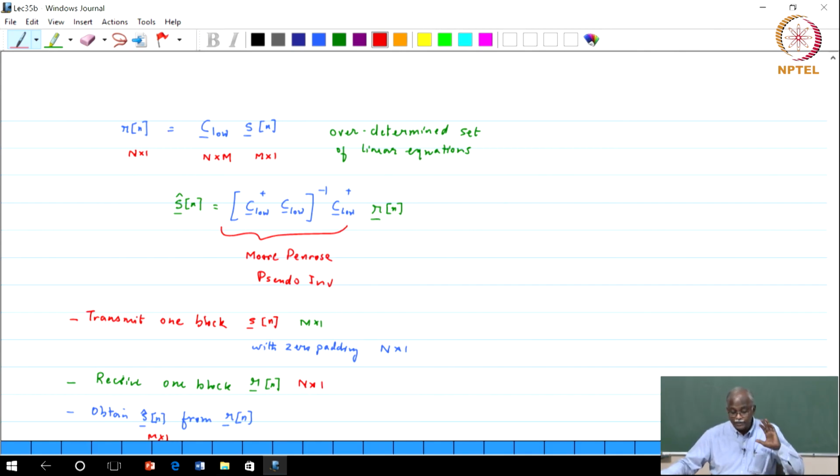Basically this is a channel that has ISI, but we have been able to do the 0 padding and bring the whole thing together so that we can then obtain it in this form. And why did we go through this matrix? You may say, well, I already have this intuition, you do 0 padding, I will get it. See, it is not trivial to go from scalar to matrix.